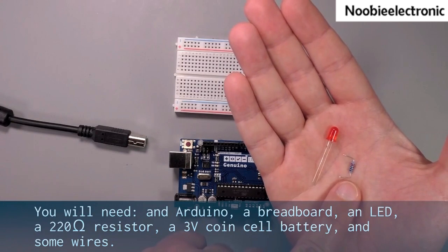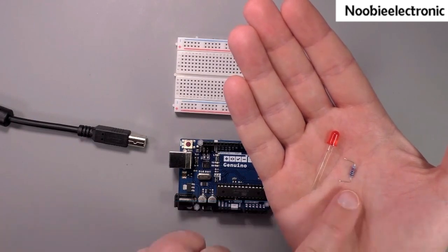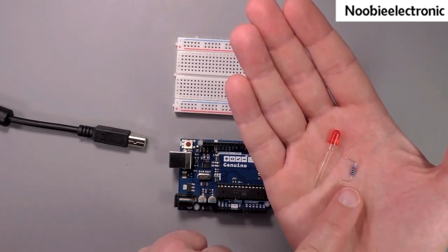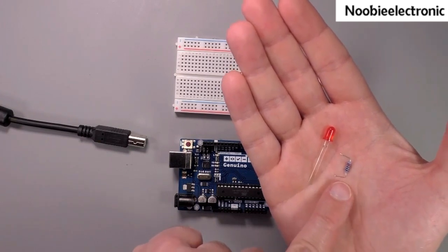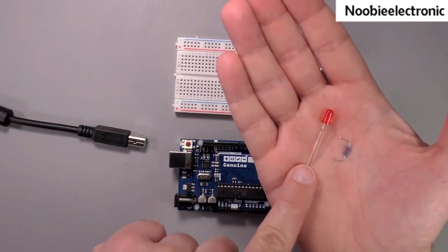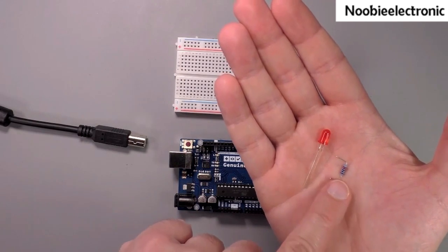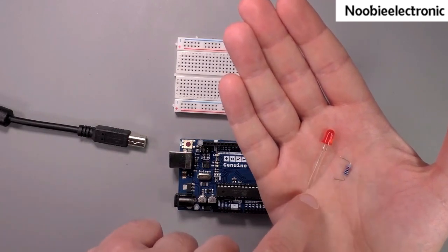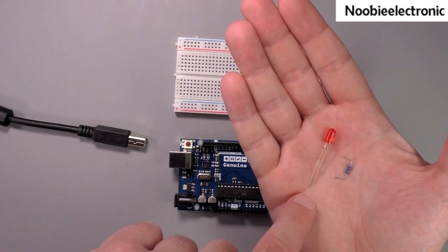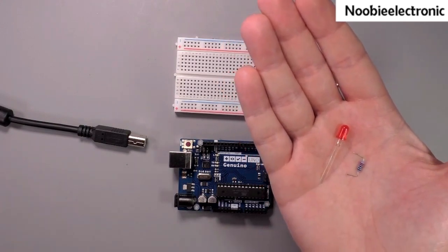The resistor that I have here is 220 ohms, but if you don't have the exact value, you can go for something larger. Even up to 1 kilo ohm will be able to work with this circuit. It's just that the larger the resistor is, the fainter the light coming out of the LED will be. But don't go for anything smaller, because the smaller the resistor is, the more current will flow through the LED, and the more likely that eventually your LED will expire and will be damaged.